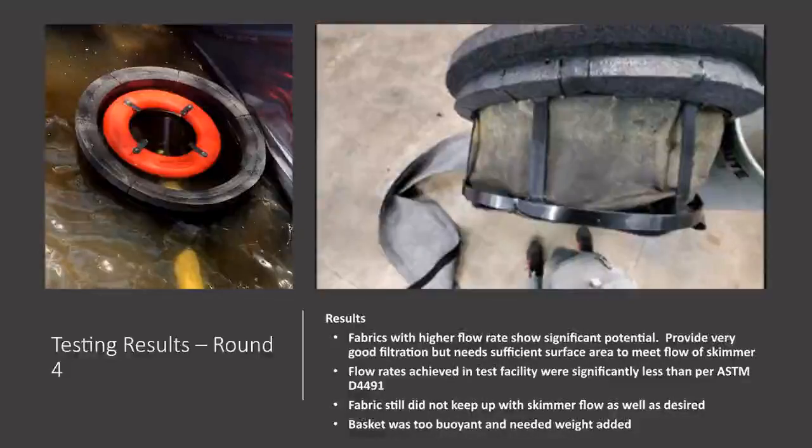We also noticed that the flow rates achieved in the test facility were significantly less than per ASTM D4491 testing of the fabrics. The use of the skimmer to pull flow through the fabric resulted in a much lower flow rate. The fabric did not keep up with the skimmer flow as well as desired, and in this case the basket was too buoyant and actually tended to float up with the skimmer, and so additional weight needed to be added.